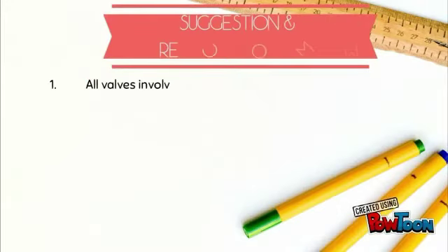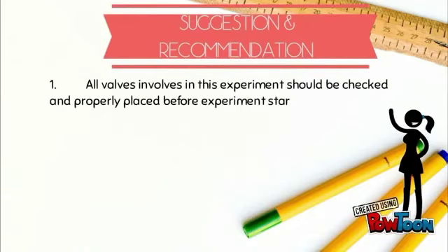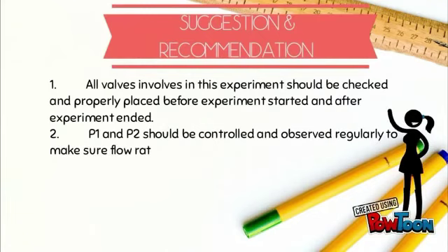Suggestion and recommendation. First, all valves involved in this experiment should be checked and properly placed before the experiment starts and after the experiment ends. Second, P1 and P2 should be controlled and observed regularly to make sure the flow rate is constant throughout the experiment.